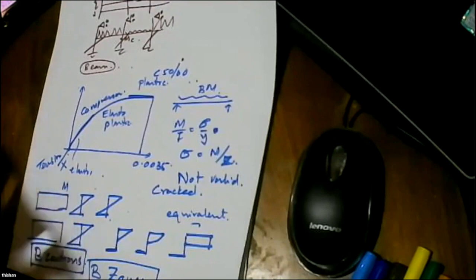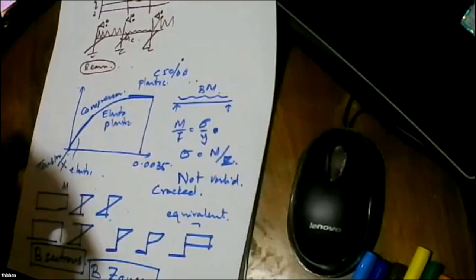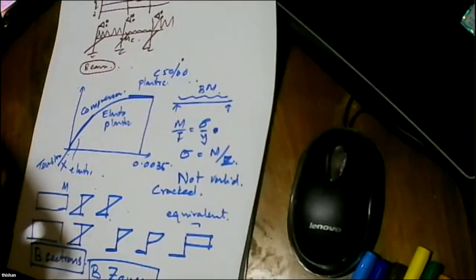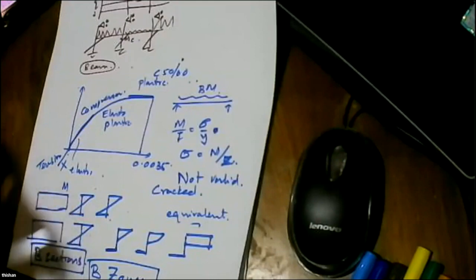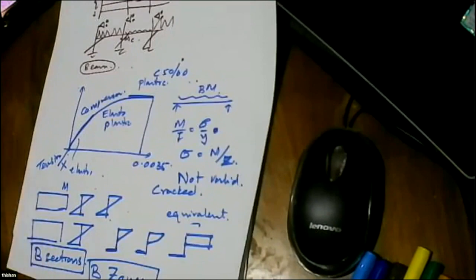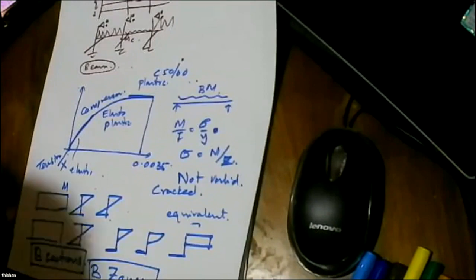So we solved the problem that way, and we reduced the number of piles by 50%, because now our piles will be carrying much more. A 1200 pile can go up to 12,000 kilonewtons, and a 1500 pile can go up to 17,000 kilonewtons. To allow for that, we have to ensure that the pile has shaft capacity. For the shaft capacity, we said, instead of using 30 megapascal cube strength concrete, let's use 40 megapascal cube strength concrete.